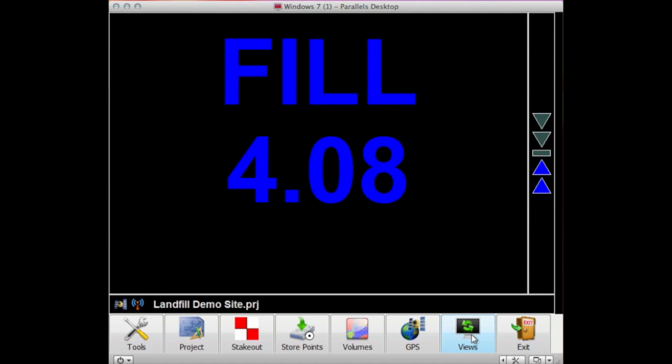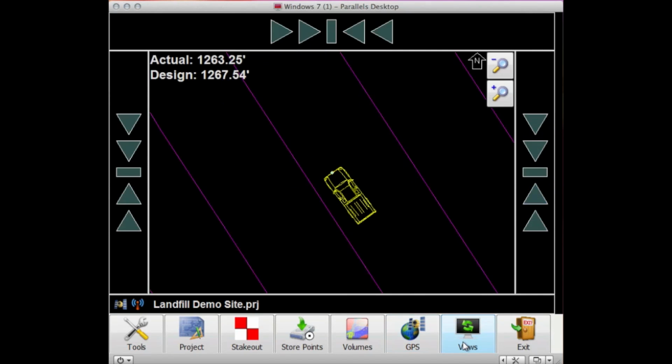If you're using, and this is cut fill only with a light bar, some bulk earth moving applications may prefer just to have a cut and fill viewing on their screen. This screen offers dual light bars for cut and fill, and also if I had a guideline or picked a steering line, this would guide me left or right to maintain that particular line.